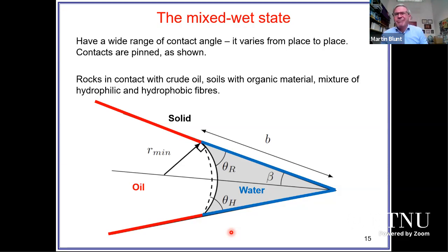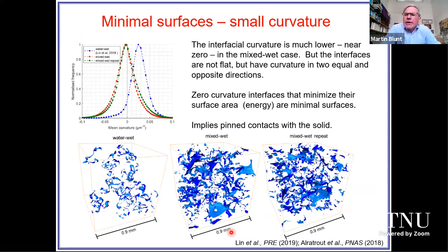Well, you're not going to stuff crude oil into these fibrous layers, but you can have fibrous layers made of plastic that are naturally oil wet, or fibrous layers made of, you know, cotton, for instance, or carbon, actually in this case, carbon, which are naturally water wet, and you can also coat the fibers. So what you have in a gas diffusion layer is a mix of water wet and oil wet, or hydrophobic, not liking water, strands together. Okay. So let's test this out.